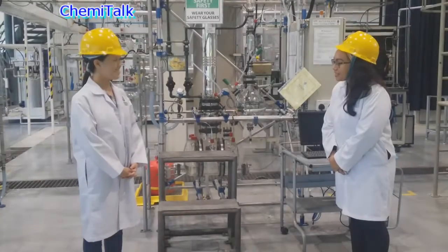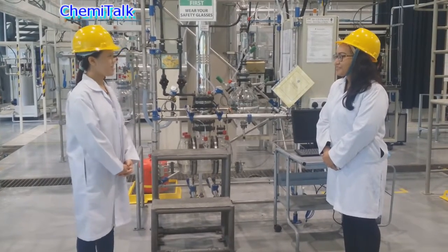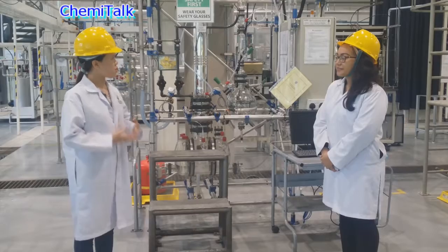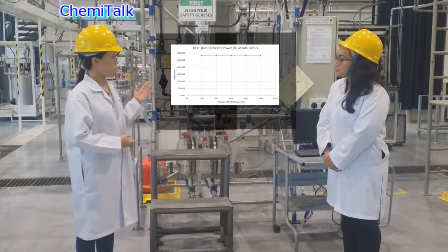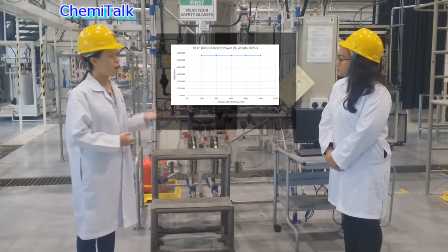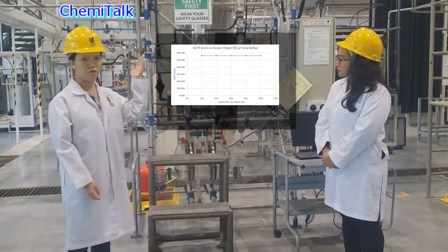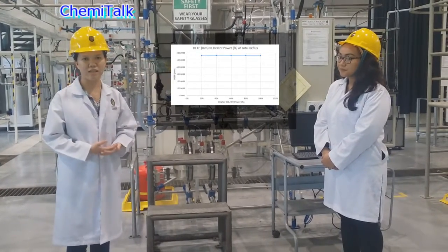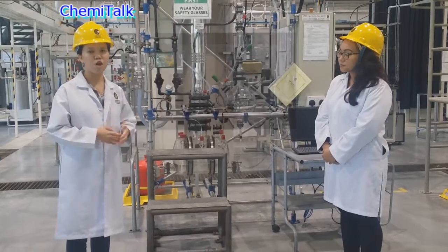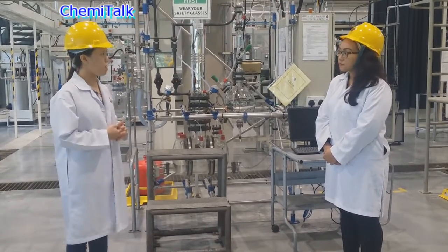That's very interesting. How was the result obtained from the experiment? Can you briefly explain to us? Yes, of course. The graph being shown here is the graph of the HETP of the column against the heater powers of the reboiler. As we can observe from the graph here, it shows a horizontal straight line which indicates that the HETP is the same for all the heating power, that is 560 mm.